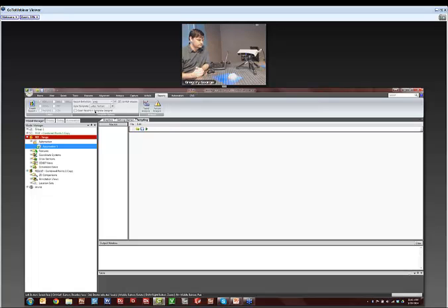Let's talk a little bit about some of this. We got some technical questions here, actually a few just related to GOM. We use a GOM system right now. How is your accuracy if we're measuring on SLM metal parts? This device, especially based on its price point, is between 60 to 112 micron accuracy. I know GOM has a wide range of accuracies as well, and some of them are very accurate, and some of them are a little more loose.